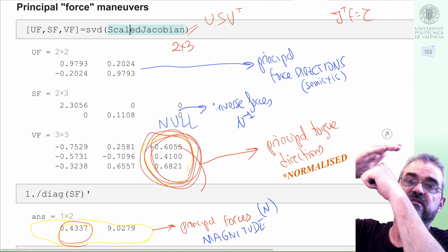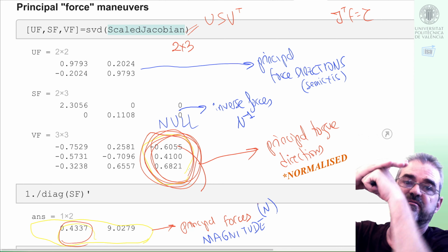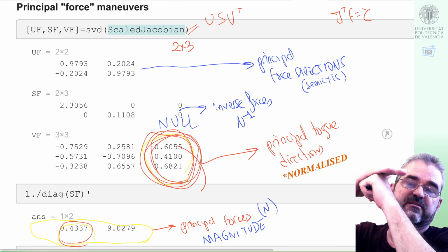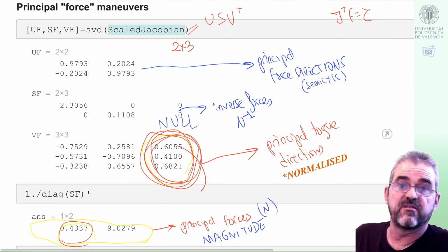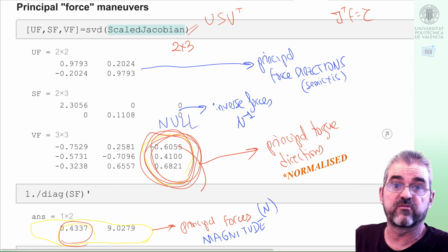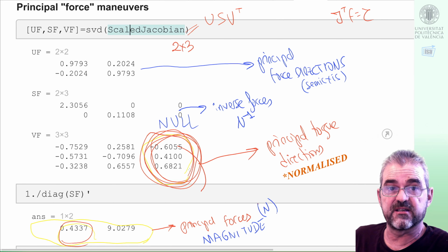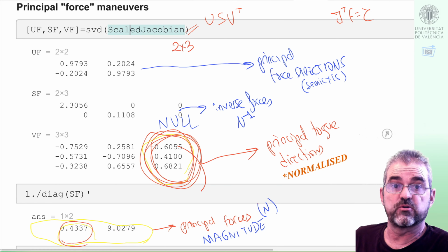So it's kind of exerting zero force and moving my elbow, whatever, without moving the end effector. Of course, if our problem statement is that we should compensate an end effector force in order to avoid robot motion, then I should not apply a torque in this null direction. Well, this is what the SVD tells me.